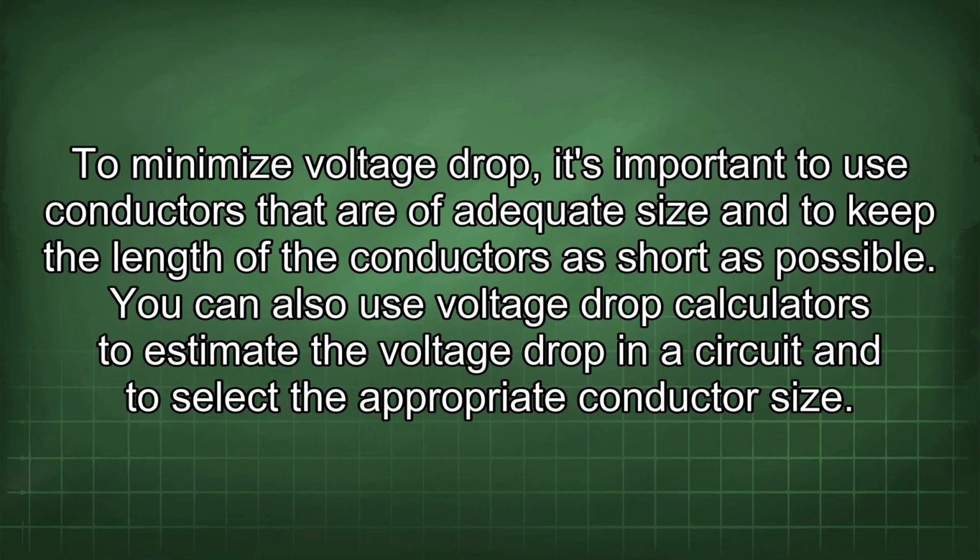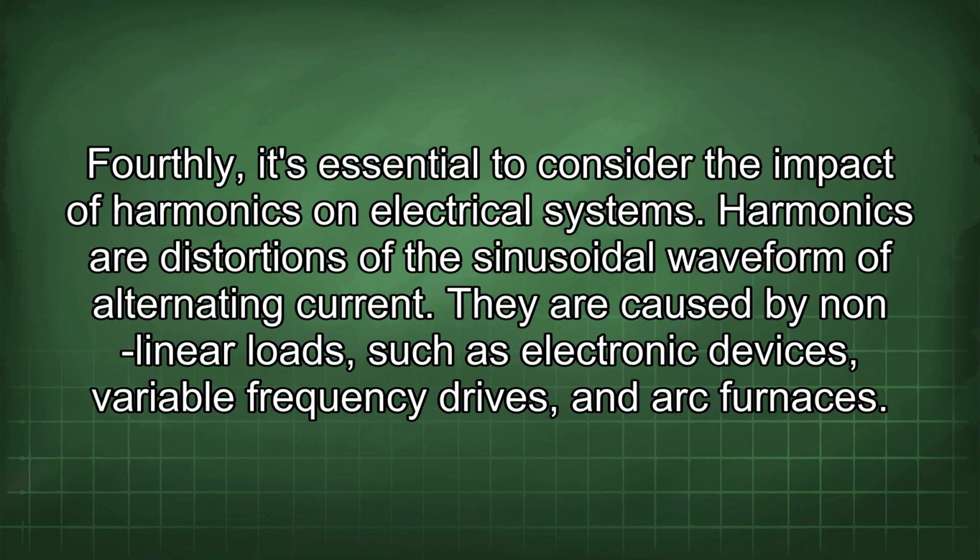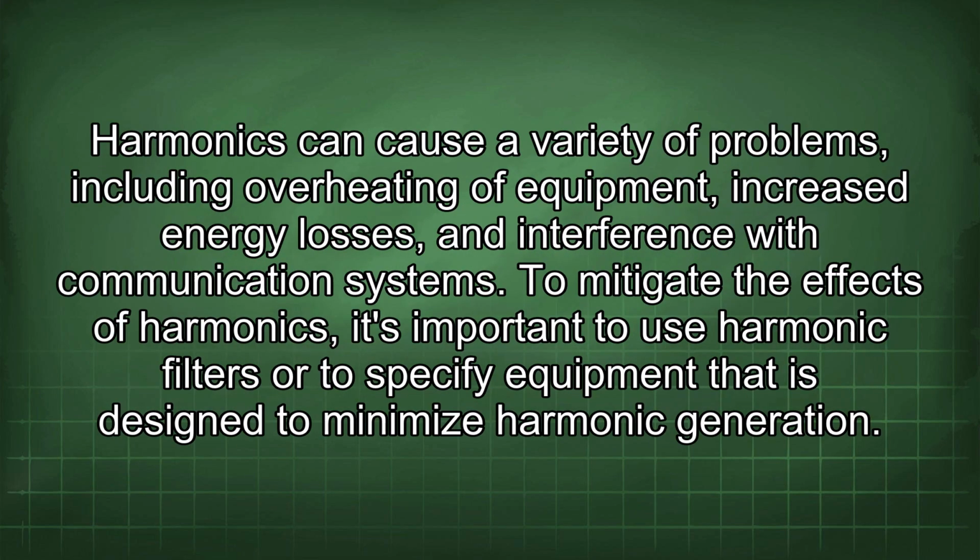Fourthly, it's essential to consider the impact of harmonics on electrical systems. Harmonics are distortions of the sinusoidal waveform of alternating current. They are caused by nonlinear loads, such as electronic devices, variable frequency drives, and arc furnaces. Harmonics can cause a variety of problems, including overheating of equipment, increased energy losses, and interference with communication systems.